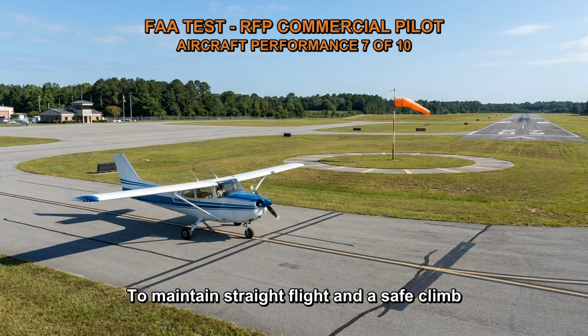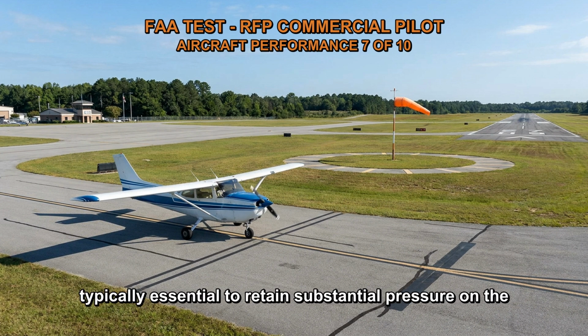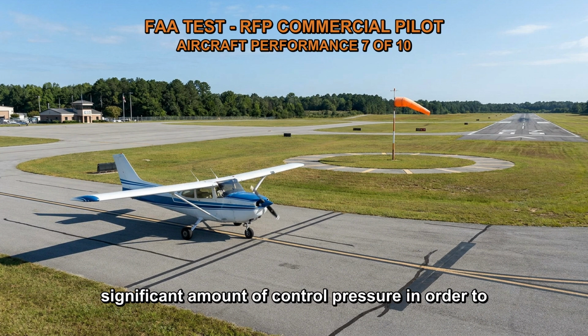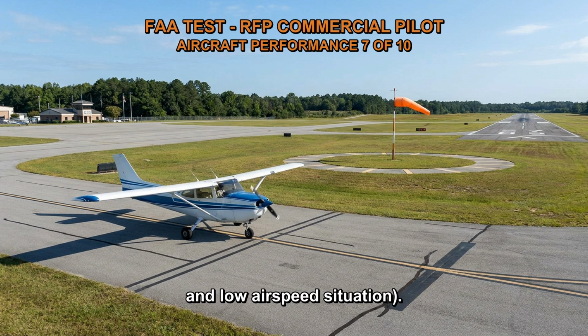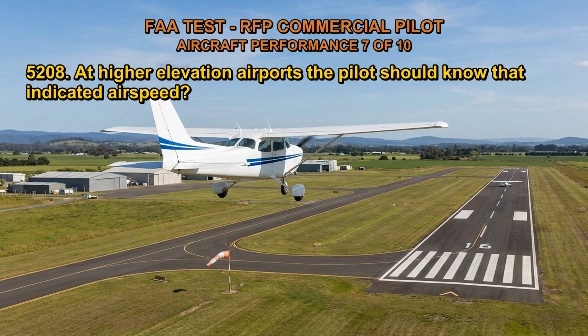To maintain straight flight and a safe climb attitude when takeoff power is delivered, it is typically essential to retain substantial pressure on the controls. Application of the maximum permissible power necessitates a significant amount of control pressure in order to maintain a constant pitch attitude, since the airplane is trimmed for the approach, a low power and low airspeed situation. The aircraft's nose tends to rise abruptly when more power is added, and it veers to the left.